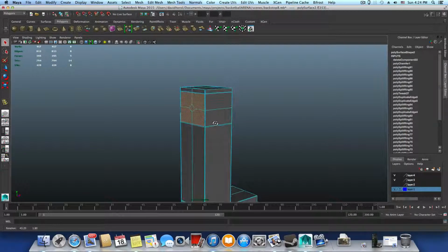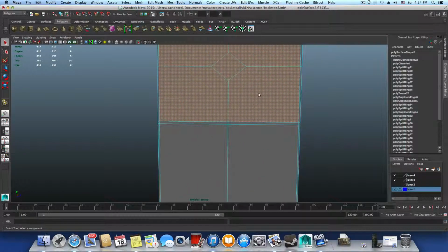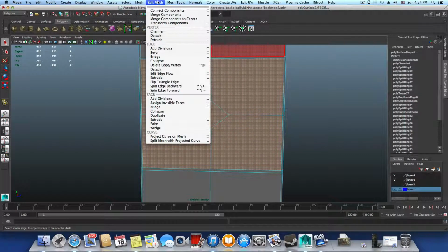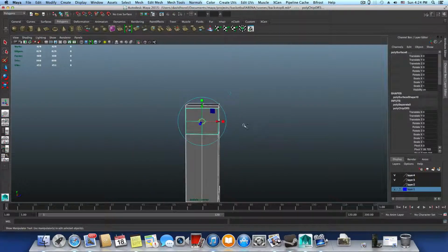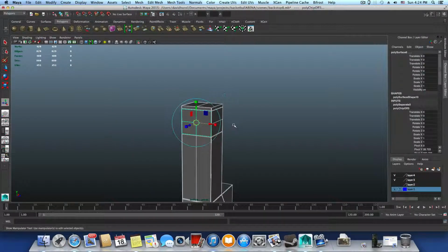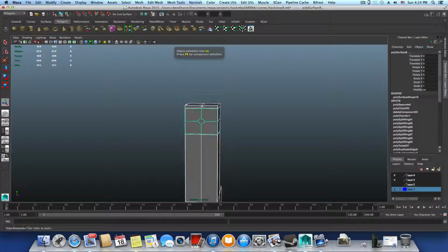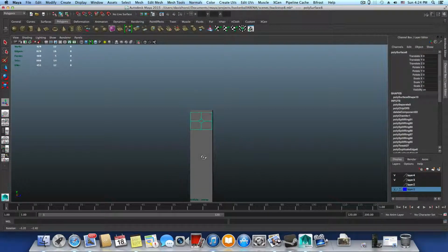Okay, I want to duplicate these faces, only this surface here. I'm gonna go over to edit mesh, duplicate. Now I'll just duplicate it. Okay, the surface is still there, but now there are 2 different surfaces like that. So I'm gonna press F8 3 times, and then you will see this one in green wireframes and this one with white wireframes. Hold down Control and select this to unselect it.